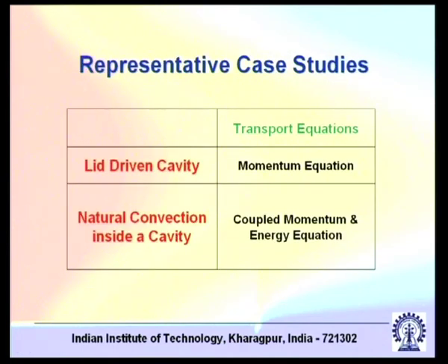Now we will go through some representative case studies. Two of the interesting case studies that we will go through are, one, lid driven cavity flow. There is a cavity in which the top lid is driven with a particular velocity and that induces a motion. This is a standard benchmark problem in CFD, known as the lid driven cavity problem. And then natural convection in a cavity, where you need to solve coupled momentum and energy equations.